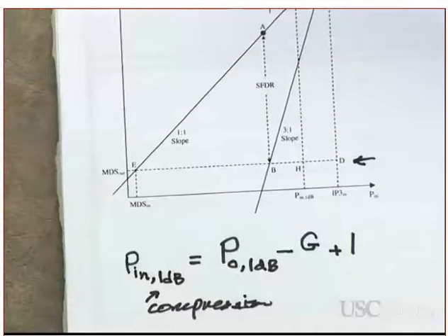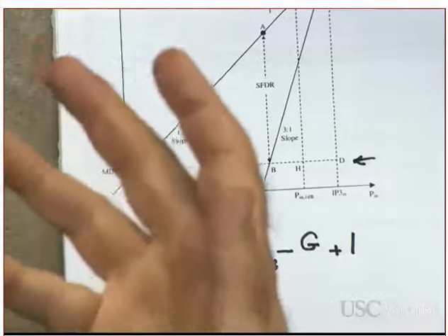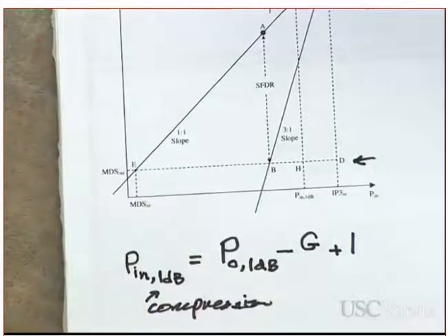Did you get my point? If the question does not give you any detail about the signal to noise ratio, in the RF industry, the MDS is usually taken to be 3 dB above the noise floor. Now, the first question we need to ask ourselves is, how do we calculate the noise floor? I will show you that in just a second.